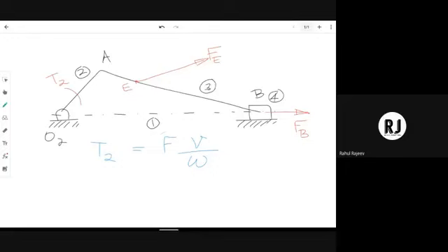Now F denotes the forces which are having effect on the system. That means forces which contribute to the work done. Now in the previous example that we took during the explanation of the principle of virtual work, we had only one force which was acting on the piston. Now there is definitely a work done due to this force. All the other forces like bearing reactions or the forces due to the cylinder on the piston all were existing, but they were not doing any work.